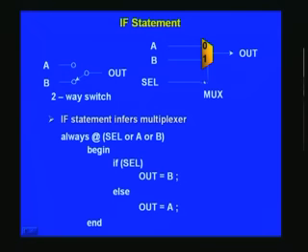This you know anyway, 0 selects A and outputs here, otherwise B is output there. And an if statement therefore infers a multiplexer, which we have already seen earlier, and we will see it once again here. It is an always block, and this is a combinational circuit as such, and there is a select and A and B inputs.